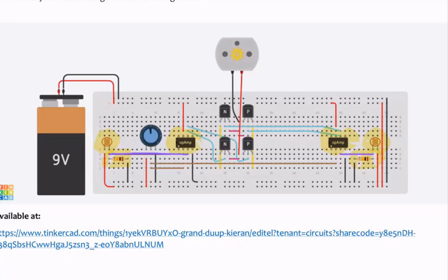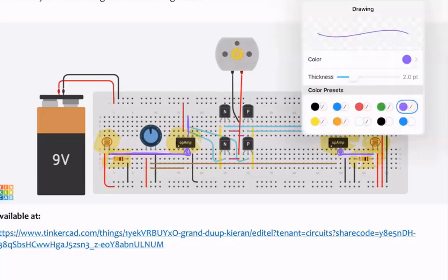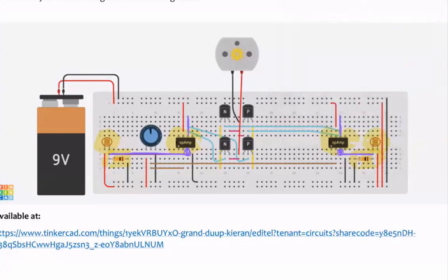So what is happening here? When the light intensity increases, the resistance decreases. That means the voltage at this terminal is going to increase. Okay, we got that part. Now the output of the voltage comparator, which is pin number 6 right here, will be high when the voltage at the non-inverting terminal, pin number 3, is higher than the voltage at the inverting terminal.